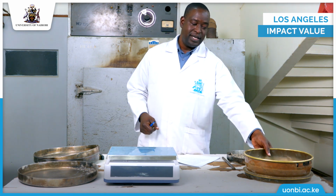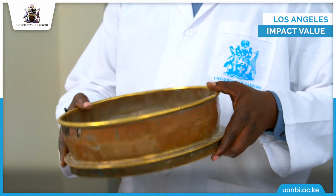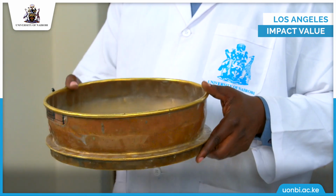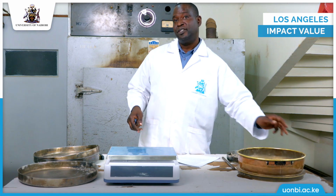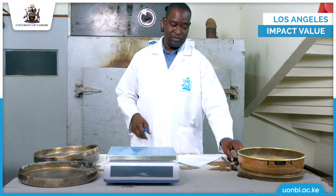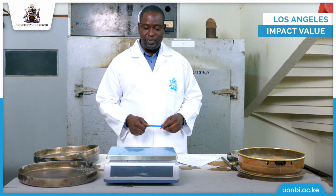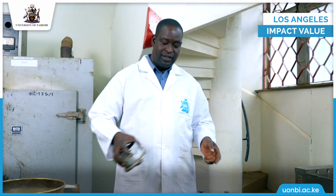We also need, for this experiment, a sieve, the BS sieve number 7, of aperture size 2.36 millimeters. We require also a wire brush that we'll use. And we also need a weighing balance to 1 decimal place.